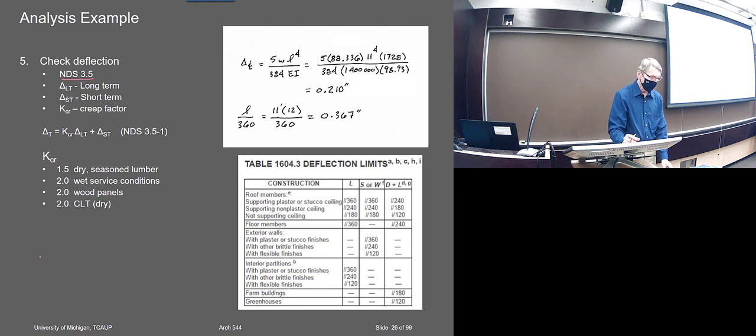And in steel, there's not much creep, right? I don't think steel creeps. Concrete, I guess, does a little bit. Wood certainly does. Over time, wood would sag a little more. And so they have a creep factor that gets applied to long-term loading. So the first thing you have to determine is how much of your load is long-term and how much of it is short-term.